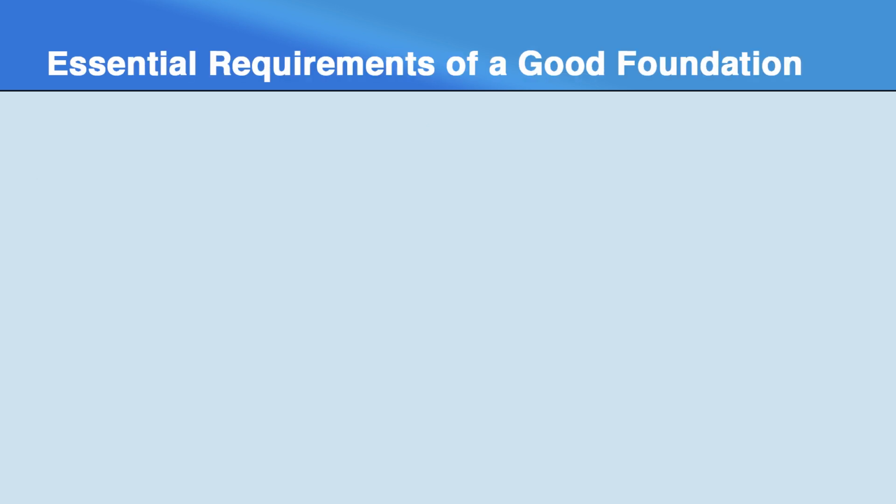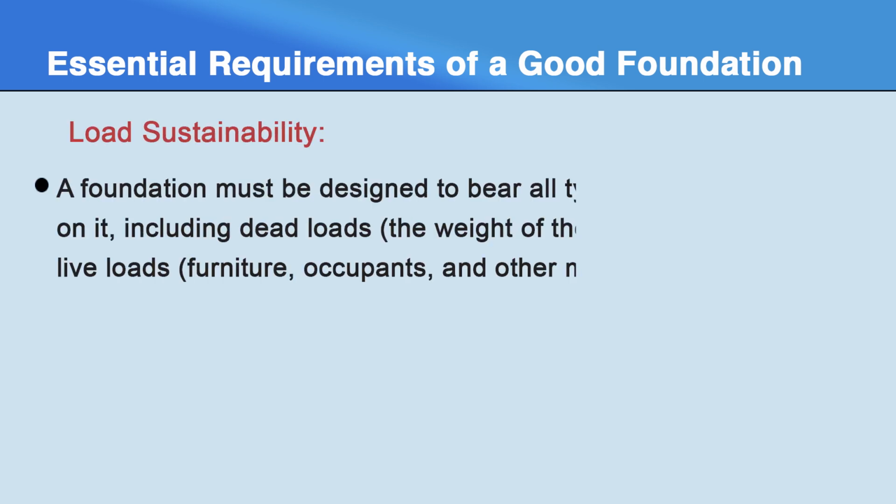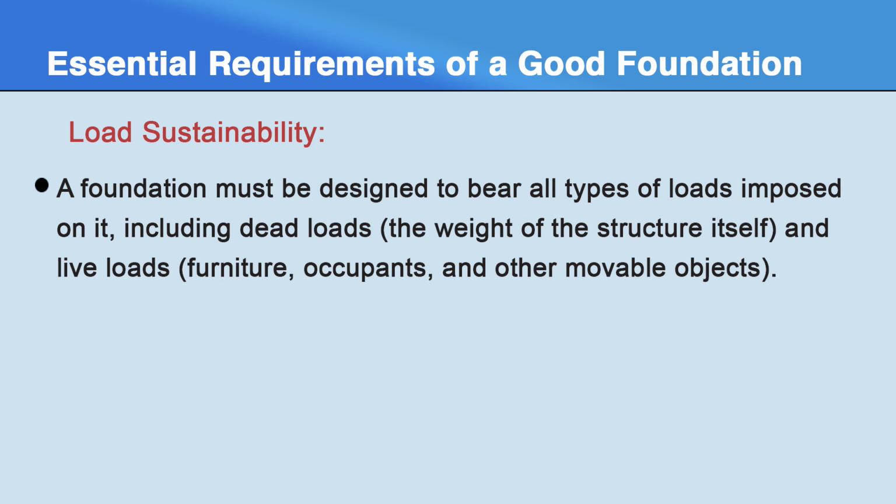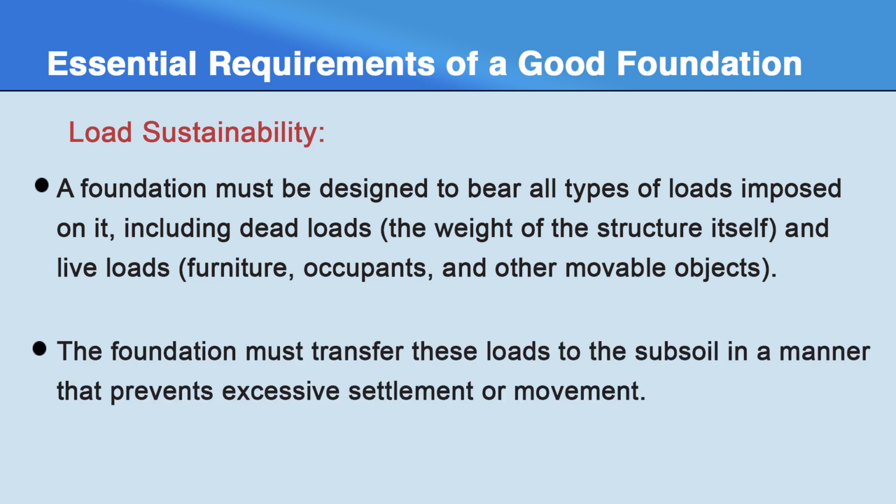The next is essential requirements of a good foundation. A good foundation must have load sustainability. A foundation must be designed to bear all the types of loads imposed on it, including dead loads. Dead load is the weight of the structure itself, and the live load. Live load includes furniture, occupants, and other movable objects. The foundation must transfer these loads to the subsoil in a manner that prevents excessive settlement or movement.